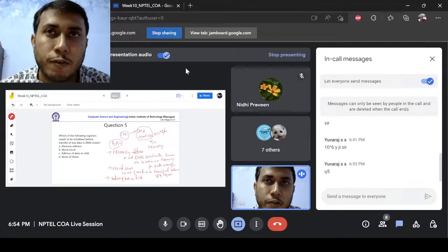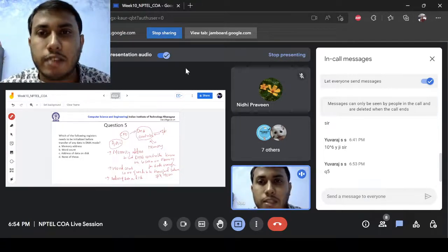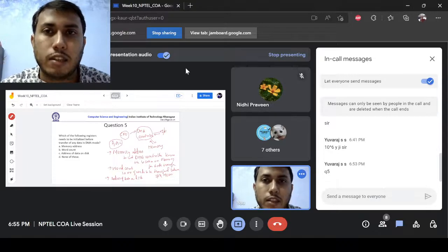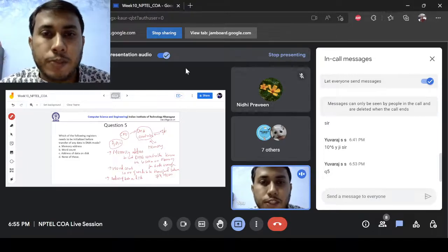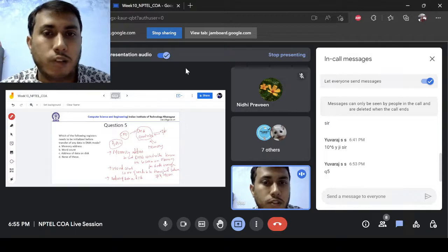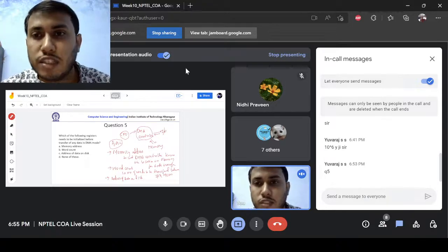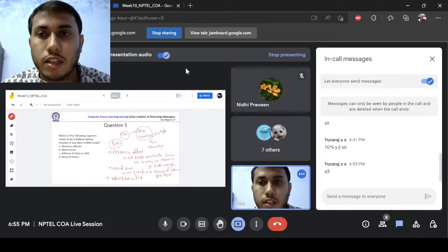As you know from the previous class, there is not much difference between memory and IO except the proceedings; the way the CPU treats them, the addressing part, is exactly the same. Each memory block has an address, and IO also has an address. So the CPU gives that IO address to the DMA controller too: this is the IO device from which you need to transfer the data. These are the 3 things the CPU writes to the DMA controller.